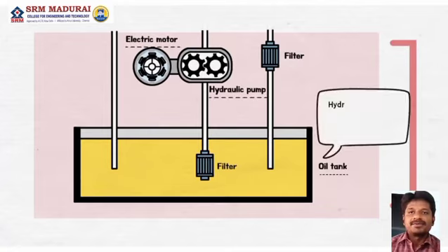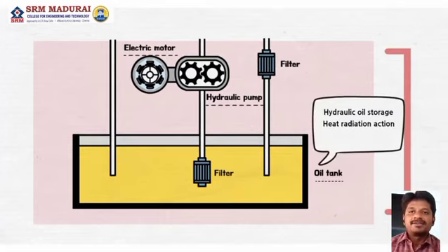An oil tank is a storage tank where the hydraulic oil is kept. This tank not only stores oil but also cools off the high temperature hydraulic oil, dissipating the generated heat, and removes air bubbles and foreign matter generated during circulation.